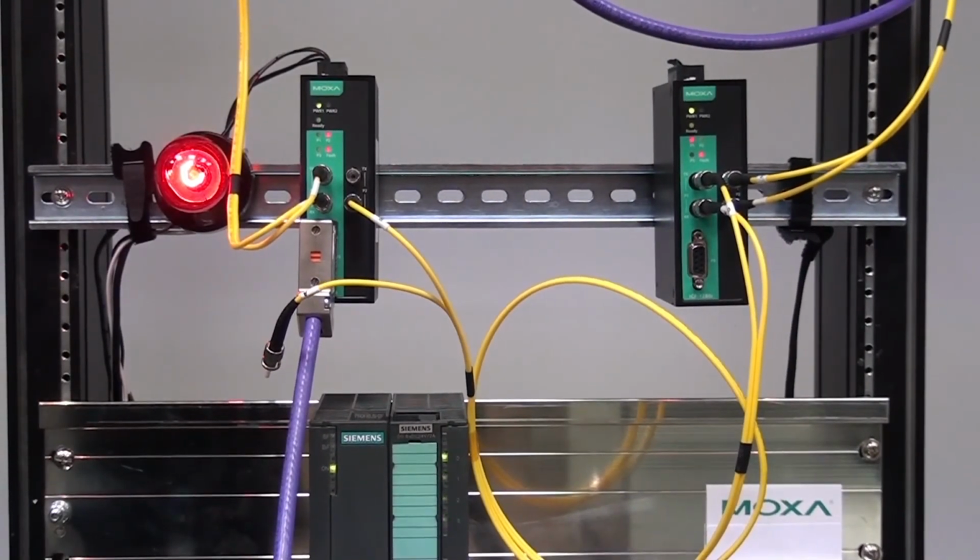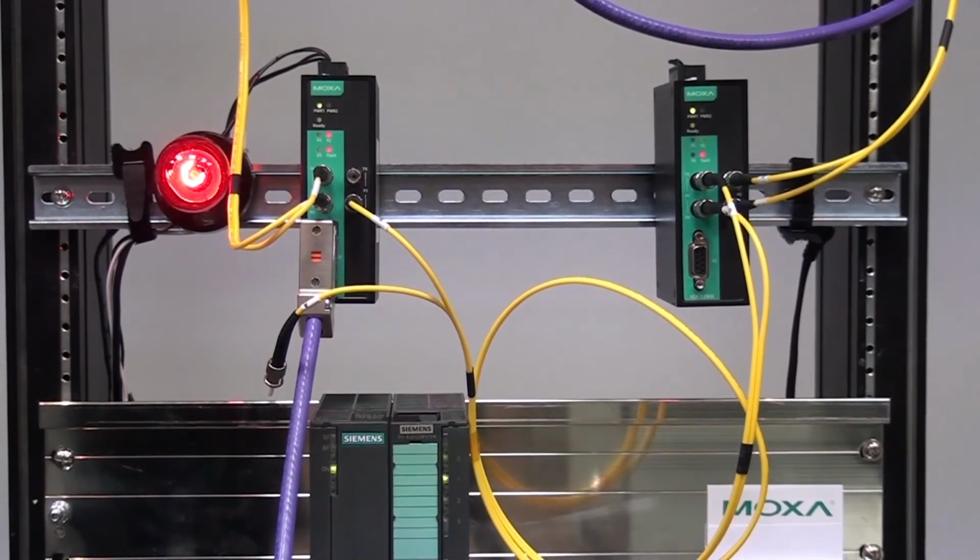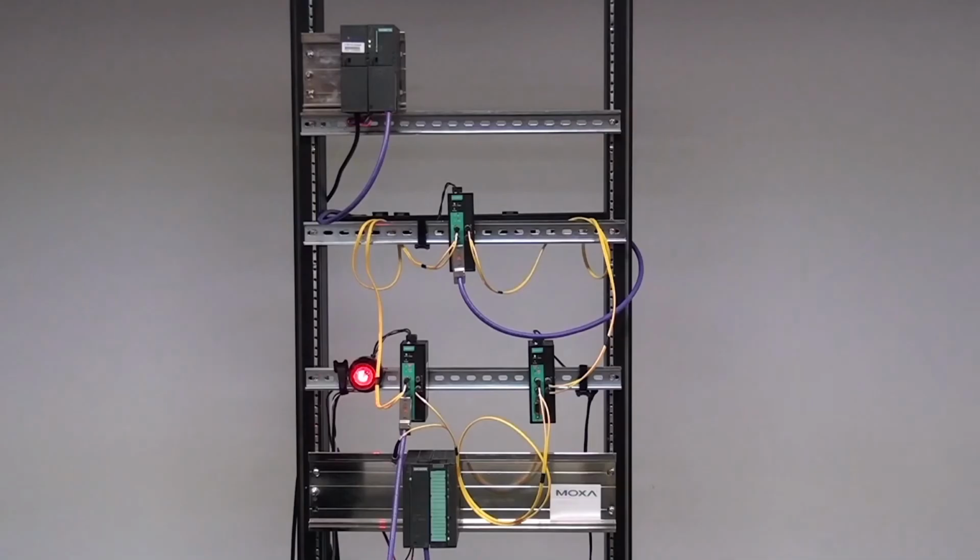Here, after we've disconnected the cable, we can see that all the LEDs on the Siemens Profibus device indicate that the communications are still normal thanks to redundancy. All the Siemens LEDs are still green. However, the LEDs on all the converters in this network will now indicate to us that there is an issue. You can even hook up an external relay alarm to the converter so that any connection issue is visible from far away.